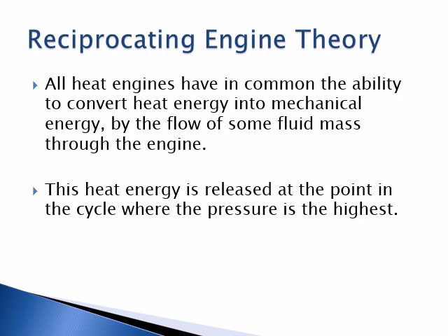All heat engines, including reciprocating engines, share one fundamental principle. They convert heat energy into mechanical energy. This is accomplished through the movement of a working fluid, usually a gas-air mixture, that flows and expands through the engine. In a reciprocating engine, combustion occurs when the pressure and temperature are at their peak, typically just after the compression stroke. The resulting rapid expansion of gases forces the piston downward, converting chemical energy into useful mechanical work. Understanding this principle is essential for diagnosing performance issues and ensuring efficient engine operation.